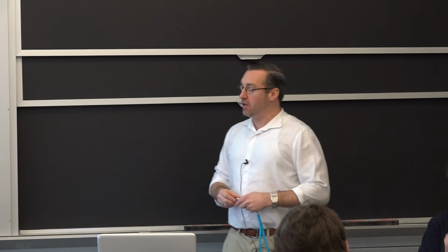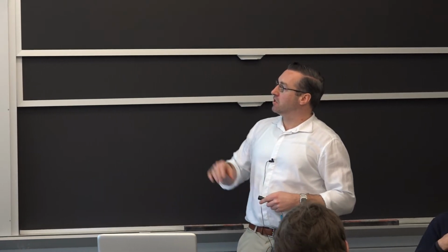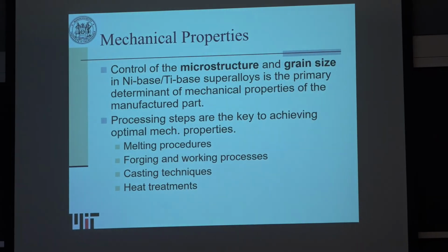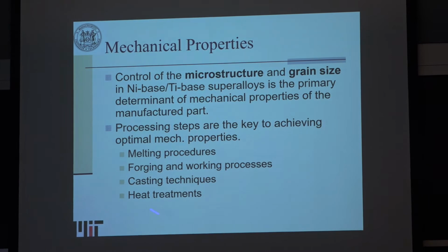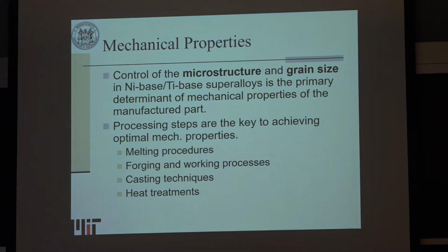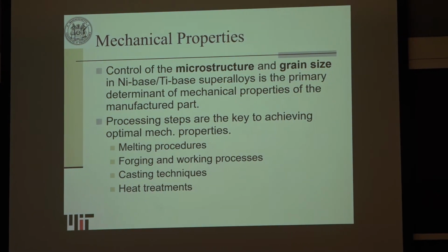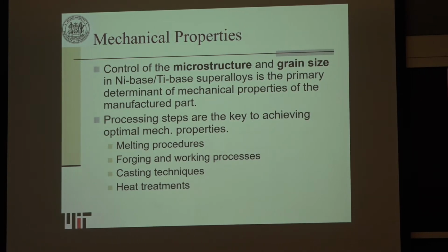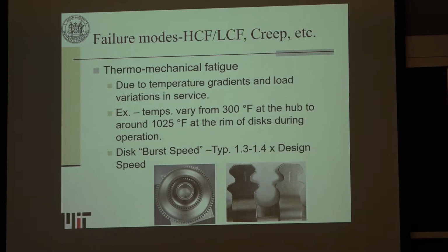So you have to make sure you have appropriate melting procedures, forging processes, heat treatments. All these things come into play. And if any one of them has upsets involved, they may have to reject these parts, and they're high value parts, so a high reject rate is unacceptable for the owners and operators.